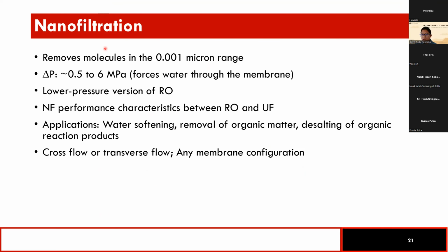Nanofiltration removes molecules in the 0.001 micron range. So this is like ions or small molecules like sugars, salts, and so on, at slightly higher pressure, from 0.5 to 6 megapascal, that's 5 to 60 bar. And this process forces water through the membrane.